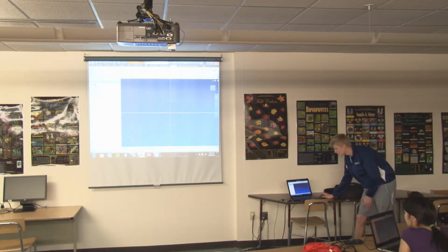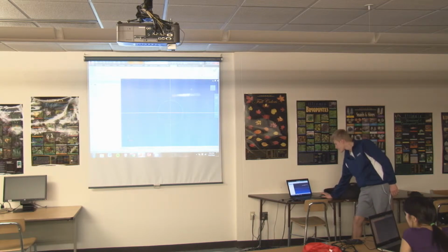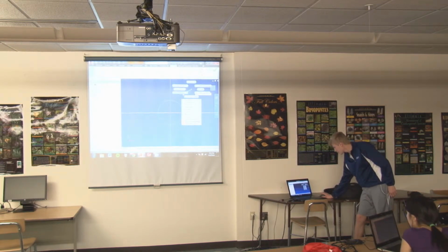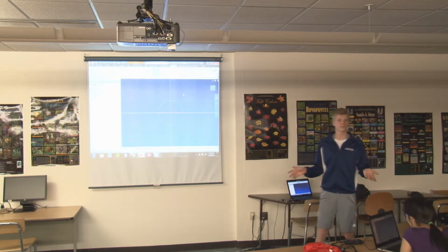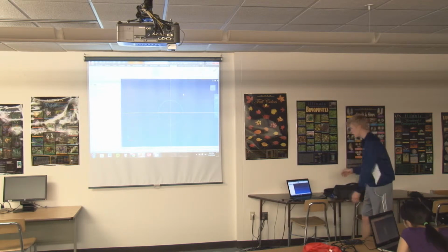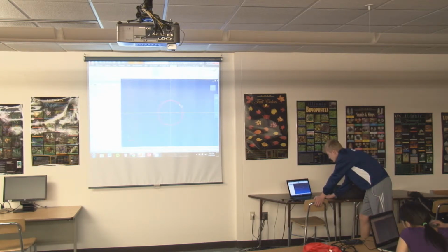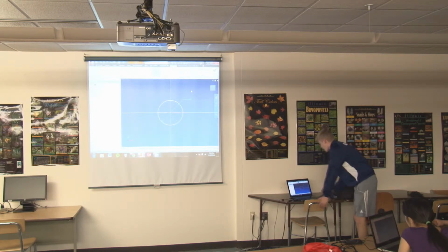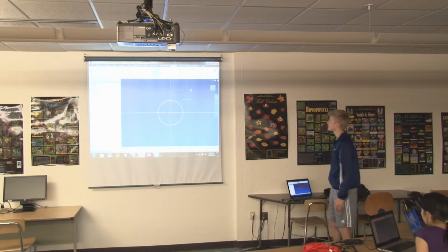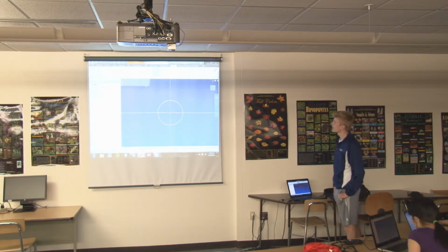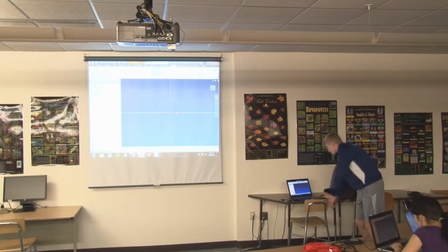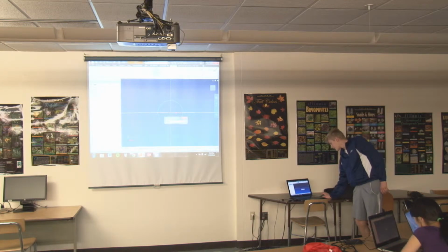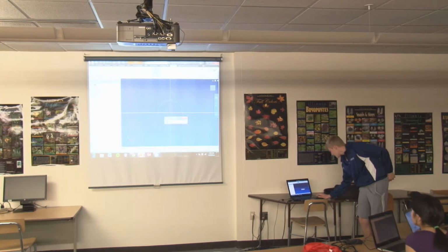Another useful feature of that right-click button is from there you can enter directly into your dimension tool, which you can use to set the sizes for every feature that you're using. So let's say you wanted to change this circle to 0.75. You would click it with your dimension tool, and then you click any arbitrary point, and once CAD loads, you can enter that dimension. Here it already exists because I already defined it. So with the dimension tool, you can just click back on the dimension that was there and enter a new dimension.